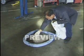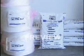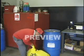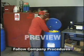Specially developed absorbent materials have been developed for spill cleanup. These products are offered in pillows, pads, sheets, tubes, and other shapes to fit all cleanup needs. Once the absorbent material is saturated, it should be placed in a large disposal drum and sealed with a drum cover.